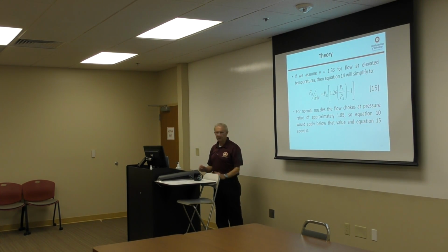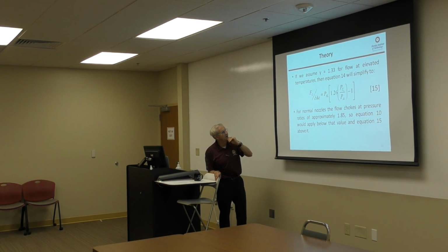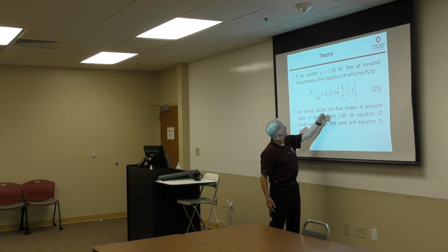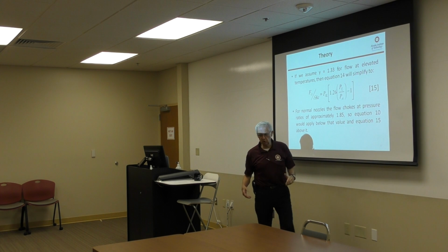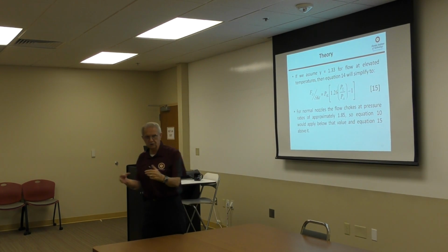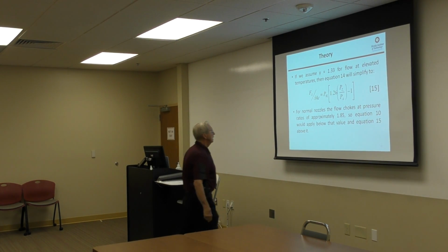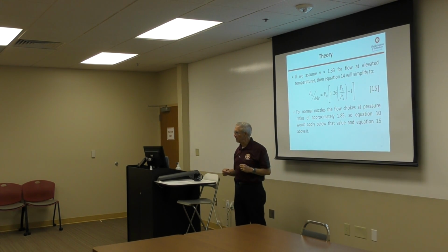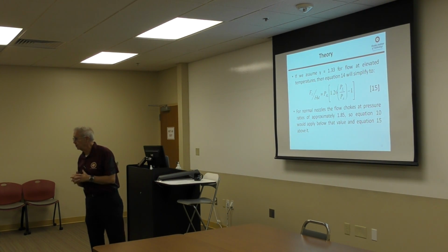we get this equation, and we can, assuming that gamma is 1.33 for fluid at elevated temperatures, then the equation reduces to a real simple one, where again, pressure sea level, we know the area of the exit, assuming this is not an afterburning engine that has all the petals and all of that sort of thing, okay? And here's our pressure ratio again. So it doesn't matter, we can use pressure ratio then for either the choked or the unchoked case and determine the thrust.